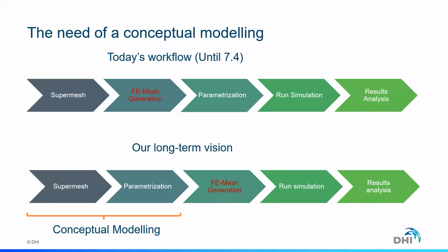The motivation for going in this direction is, as you know, FEFLOW requires a super mesh. This super mesh, either 2D or 3D, is the basis of the finite element mesh generation, and then we do a parametrization, run the simulation, and analyze the results.